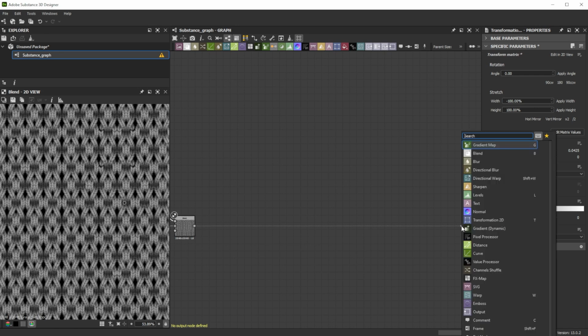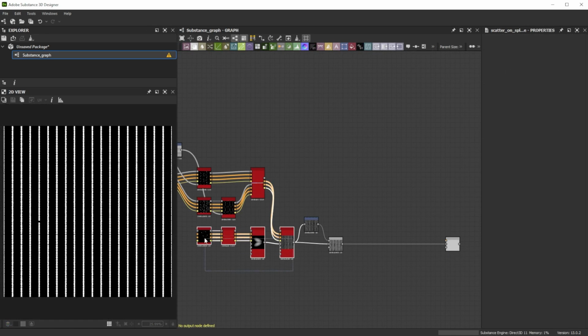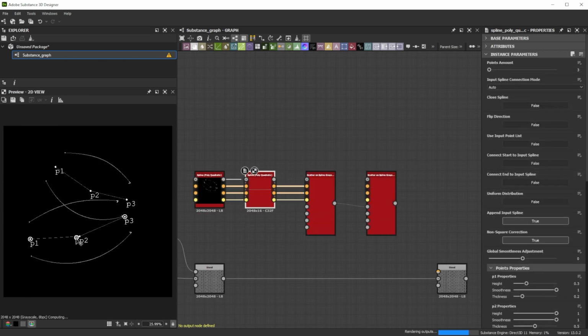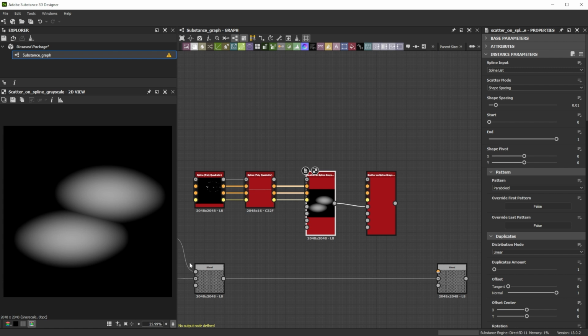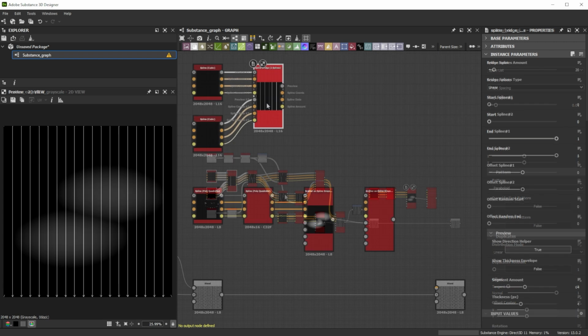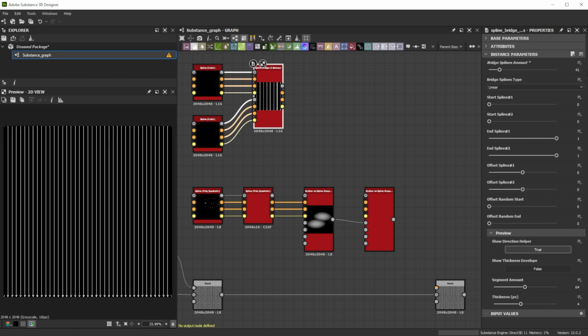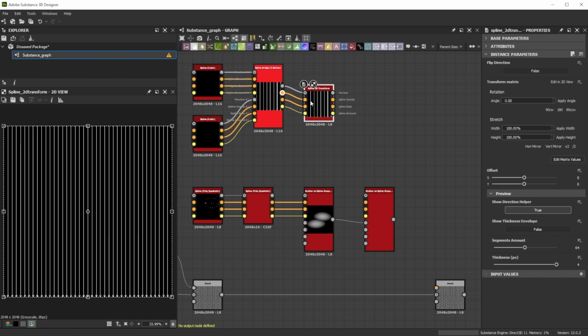Let's forward it to another blend node and switch to max lighten blending mode. Now duplicate the stitches part and reposition the splines in both spline polyquadratic nodes for a new vertical aligned stitches shape. Let's further duplicate the whole bridges part, increase the bridge splines amount to 41 and connect it to a spline 2D transform node to rotate it later on.